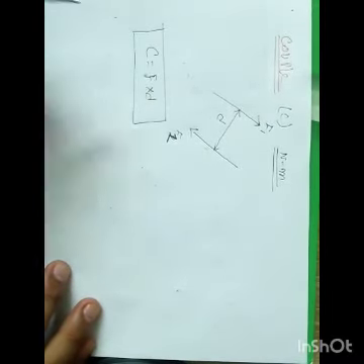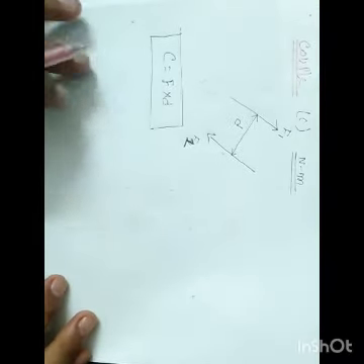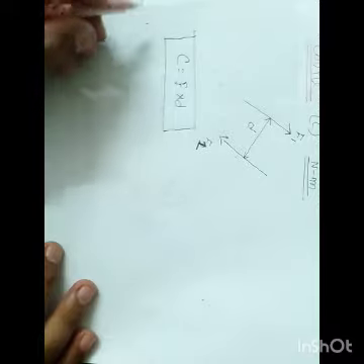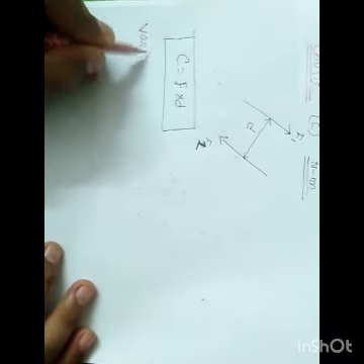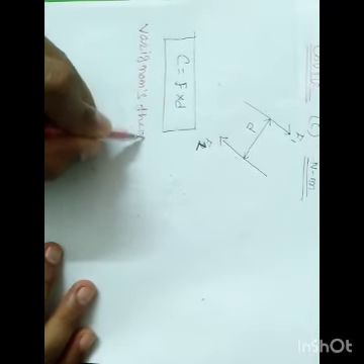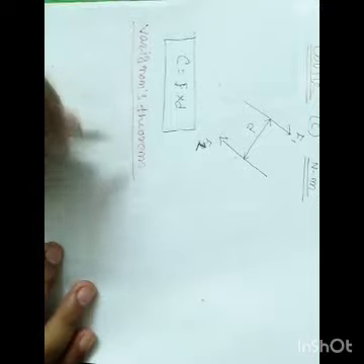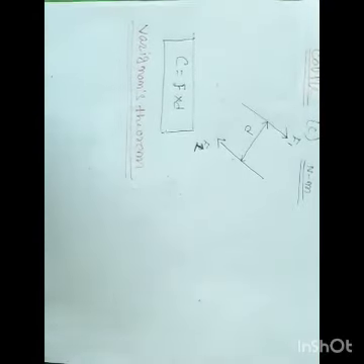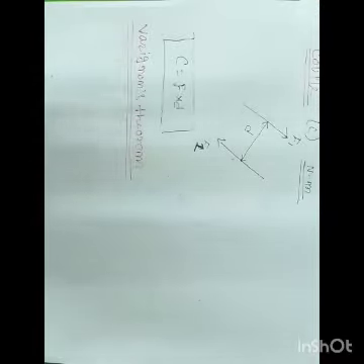This is very important, Varignon's principle; based on it we will have a number of problems, right? So Varignon's theorem, actually it's not a principle. As you remember, while we studied the system of forces, we discussed how to find the resultant and the direction. The resultant formula is R equals root of summation Fx squared plus summation Fy squared, right? Okay, now suppose any system of forces is given to you.